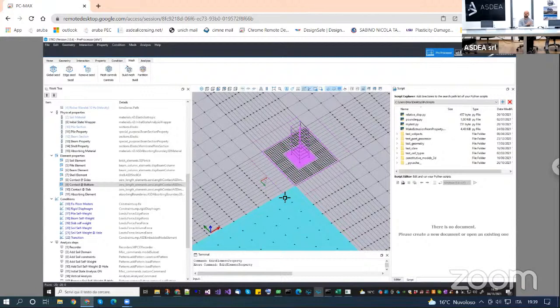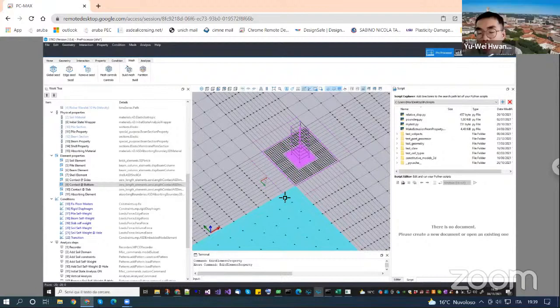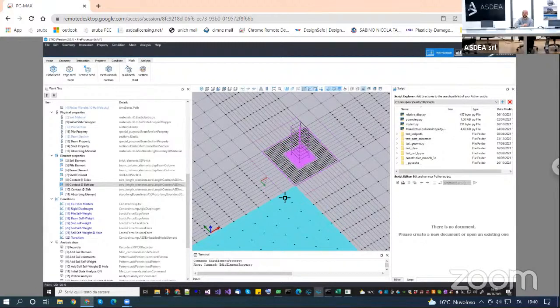It doesn't make sense to have a negative stiffness. This is pretty much the same problem that happens if you use Rayleigh damping with the tangent stiffness. What happens when the tangent goes to 0 or is negative? It can create many problems. Will it cause some convergence error, or maybe just affect the results? Also physical results.